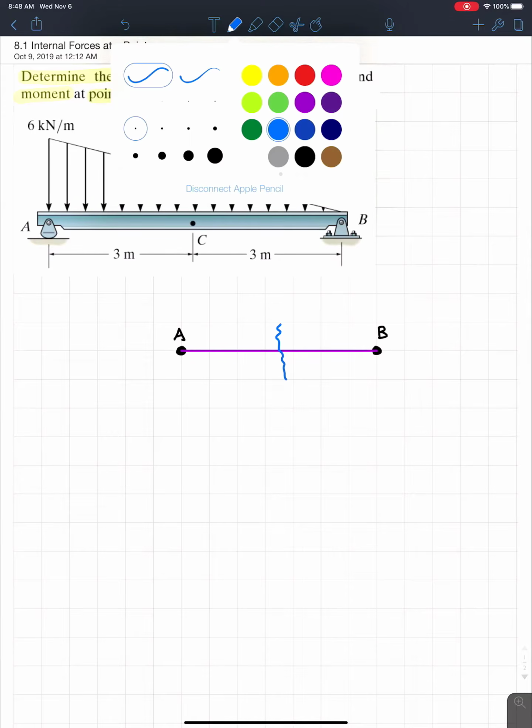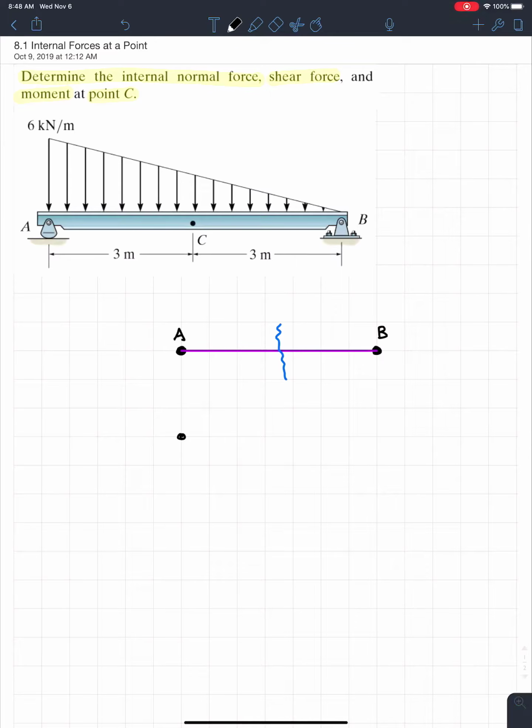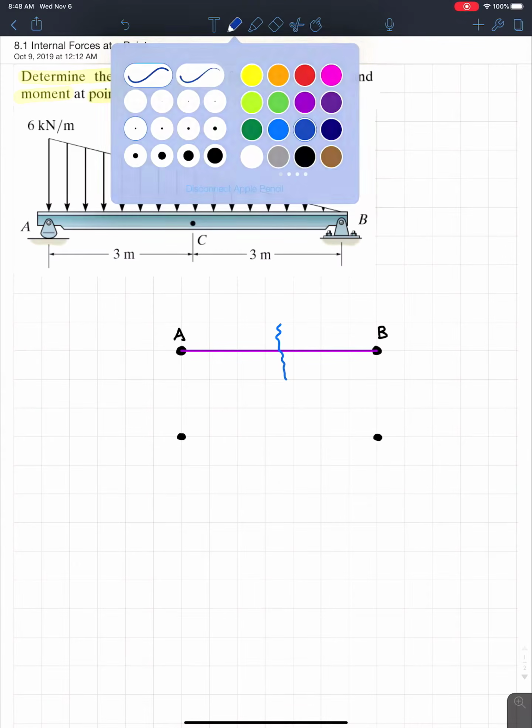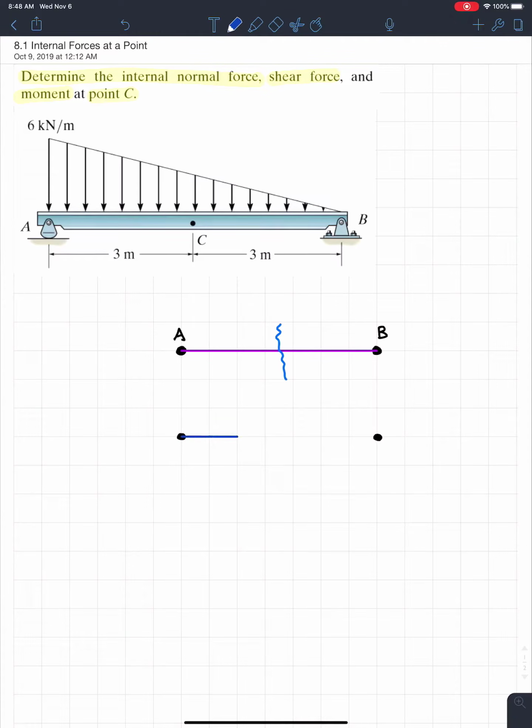And what would happen is our new joints would turn into this. So we'd have two internal forces like this. So when we cut through a truss, we had a single force on each side. So like this. And this right here would be the internal forces in a truss. Just a single axial load in a truss. So I'm going to put this as A and put this as B. And this is for a truss. So trusses were nice and simple because we cut it. We only replace the member with one load.